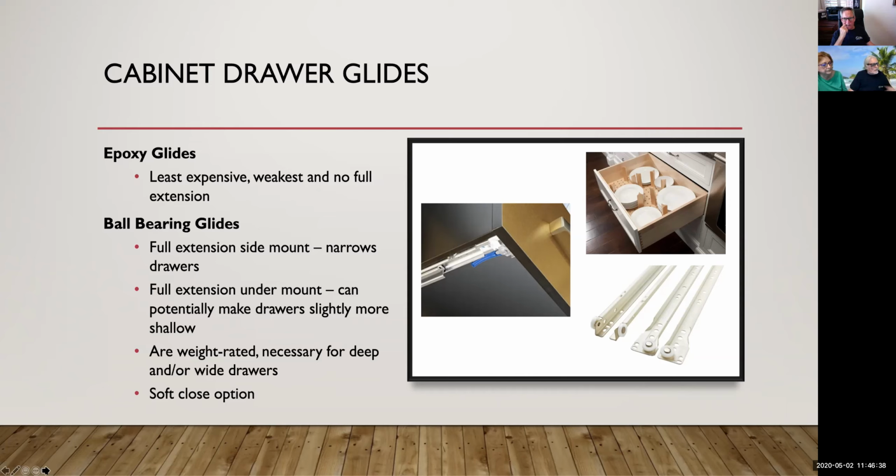I prefer in my own cabinetry to use 150-pound glides, and the drawers that I showed you earlier that are so strong, the plywood drawers with the dadoed connections. That's because you're using them as a stair step to get to the upper cabinets. Well, they're great. They're great because grandchildren hang on the top drawer and not damage it.